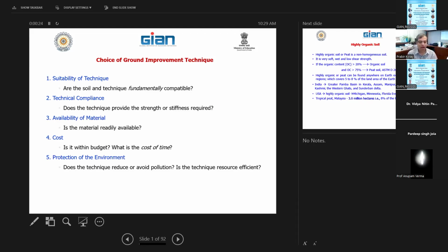So basically, the first day we discussed the mechanical methods and used different types of compactors and vibrators. And then for shallow depth, we talked about dynamic compaction, or controlled blasting for the deeper depth. And then vibro compaction, vibro composer, all these different compaction methods. Then we talked about hydraulic modification, getting rid of the water, and then the surcharge load, preloading, and also how to accelerate the consolidation.